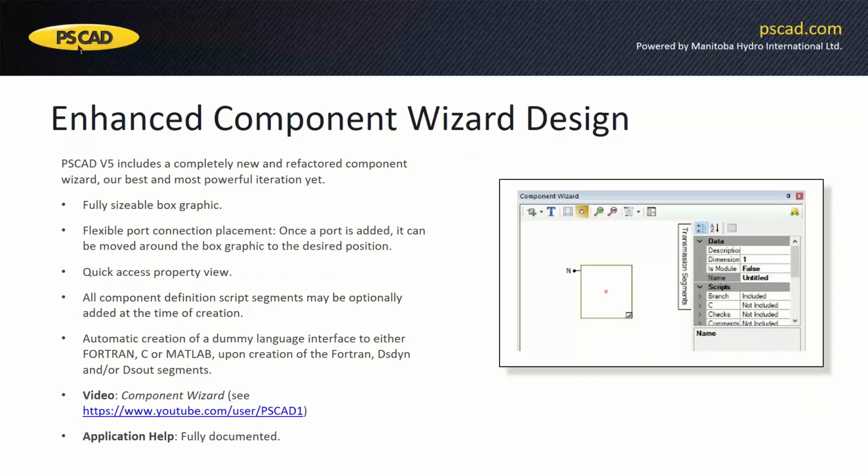The component wizard has been redesigned. This one is much more flexible, and I think easier to use. There are no more steps. And what's really nice about it is it saves your configurations for you during the PSCAD session. So if you create multiple components, you can go back to those components after the fact.